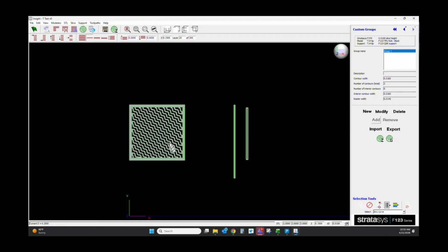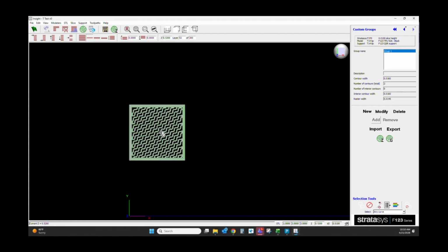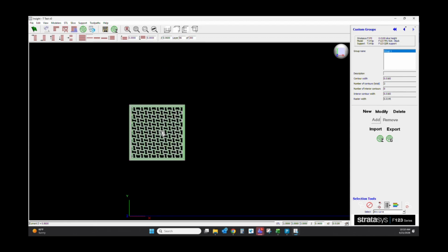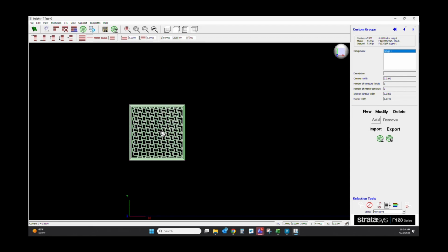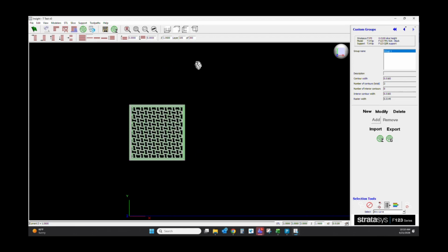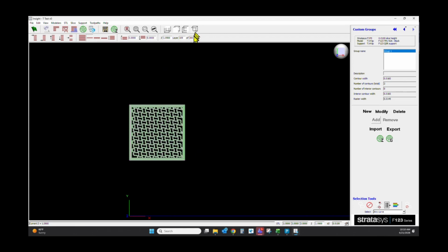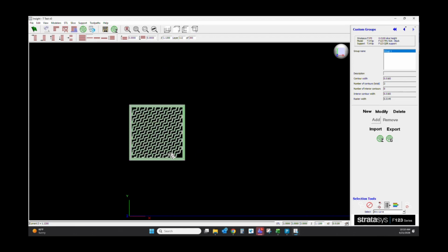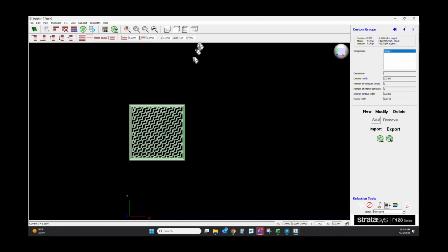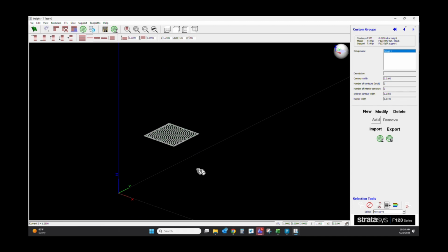And then we can go through and see how that gyroid pattern works. Pretty cool. It's self-bridging. You can make that go a lot bigger. And on TPU, the problem is the material is so soft that it tries to fall in on itself. So you have to have a little bit of support underneath. So if you use a larger diameter sparse, you'd have to create a bridging layer. And what I mean by that, I will show you.